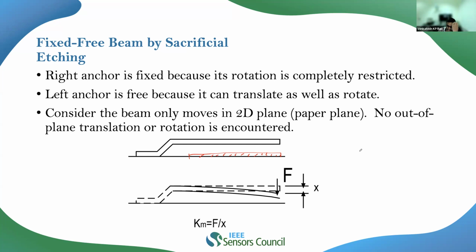In the SOI process, you don't get a bottom electrode. Please don't design any of your structures wherein you have a bottom electrode in it. I will tell you what the other ways are to design capacitive-based sensors.